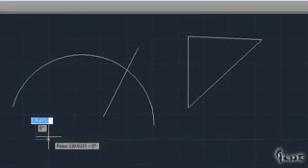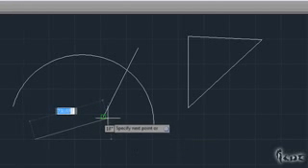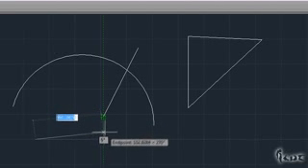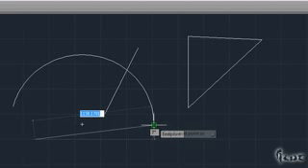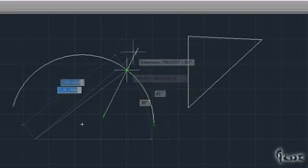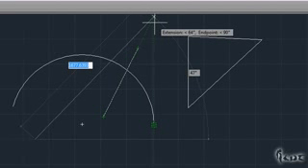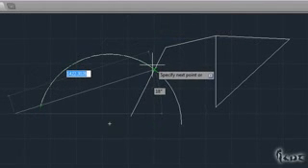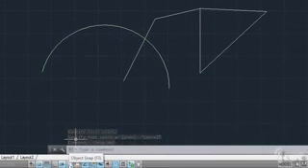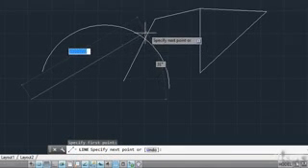These green squares or lines help you to draw precisely, through a precise axis or while connecting two different objects drawn. Squares often represent corners and endpoints of the drawings. The cross means intersection between objects, and the dashed line, the straight line intercepting an object's point. By default, your pointer will snap to these green squares, making things easier. If you want to disable snapping, click on Object Snap to turn it off. This will let you move as you like.